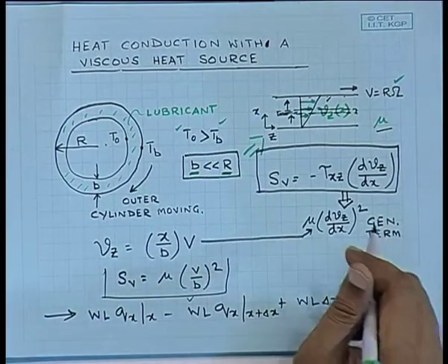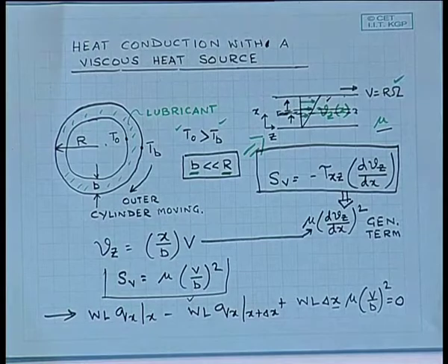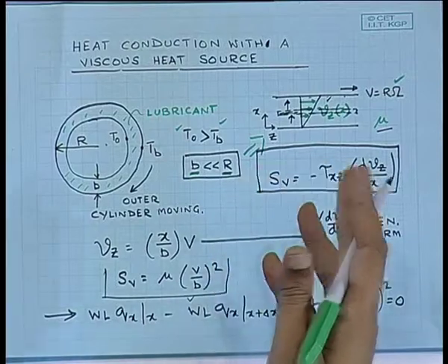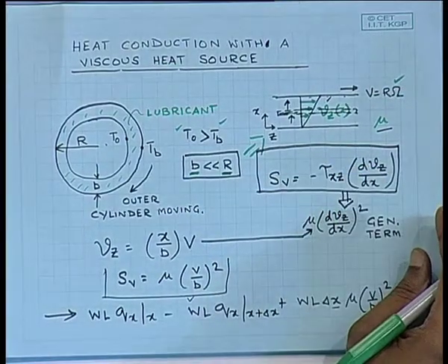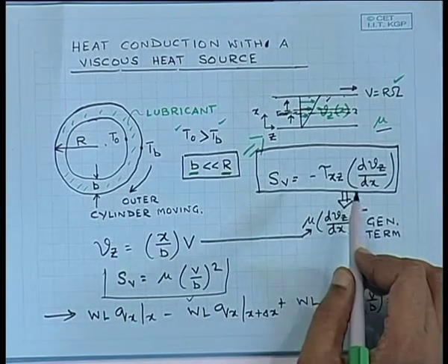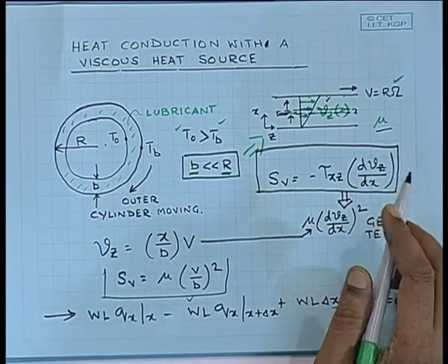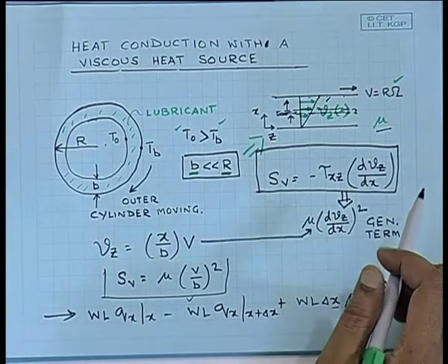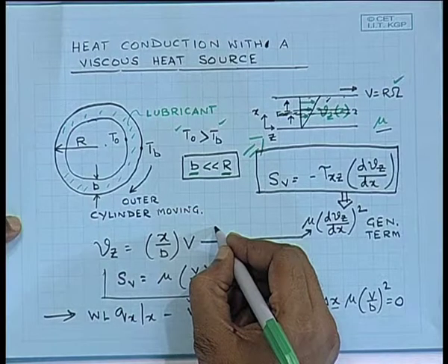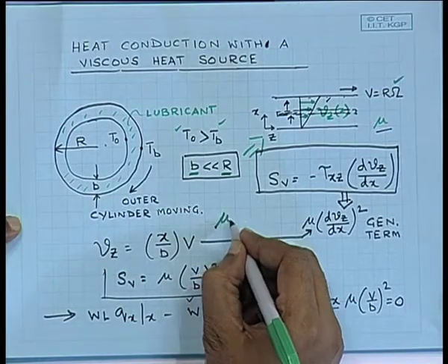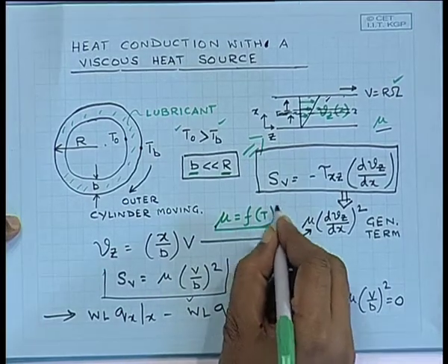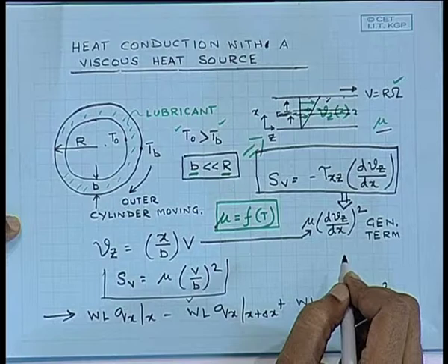So, if mu is very less, that means the velocity profile doesn't depend on mu that much. Now, if mu is very less, then obviously I would not use that liquid as a lubricant. Someone said something about mu varying with temperature. What's your comment? So we should take account of variation of mu with temperature. Okay. So, you are saying if I say that mu is a function of temperature, that makes the two processes coupled. Would you agree with that?